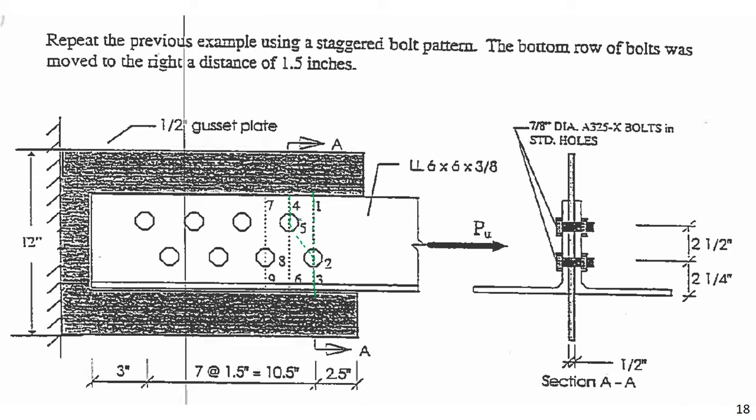Now, we cannot just look at this and say, okay, which one of these is going to control? There may be certain cases where that's obvious. This is definitely not one of them. You don't need to check every possible one. Usually you just have to check an across one and a diagonal one, because it's not going to do something really weird, like come down here and then jog over like here and then come down. It's not going to come down here and then try to diagonal all the way across like this. That's not going to make any sense. Overall, it's going to try to take the path of least resistance.